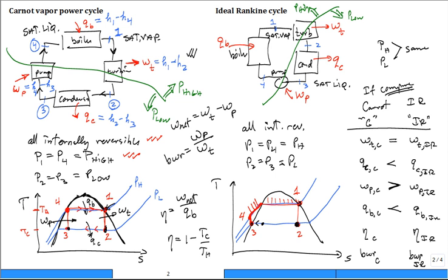Okay, what is the temperature of the liquid that goes into the boiler right there? State 4 comes right in. What is the temperature at 4 right there? What did it used to be coming in to the boiler at 4 for the Carnot? Is this temperature lower? Is there some heat transfer required to heat up the liquid water, the feed water? Do we have the same efficiency? And that's the reason why.